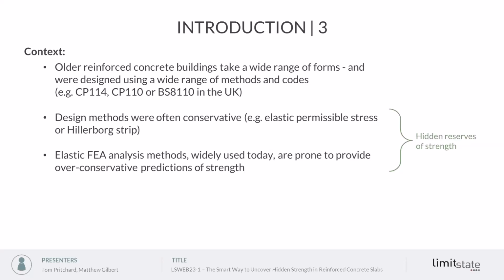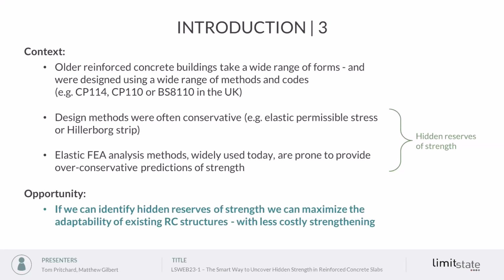On the other hand, we can use that to our advantage if we're talking about a structure that's already there, constructed, because the fact that these conservative methods are used means that there's very often hidden reserves of strength. And our task is to identify these so that when we come to repurposing an existing building, we can do so with the minimum amount of strengthening. If we can show that the structure has the strength that's needed in the new use case, then clearly we don't need to spend money strengthening.